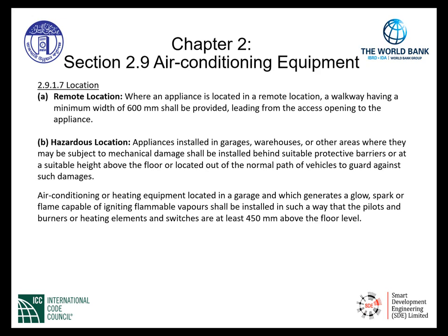Section 2.9.1.7 gives us further information regarding location. A, remote location. Where an appliance is located in a remote location, a walkway having a minimum width of 600 millimeters shall be provided, leading from the access opening to the appliance.